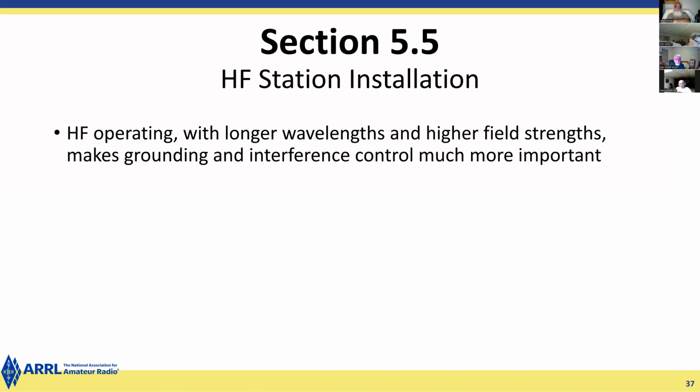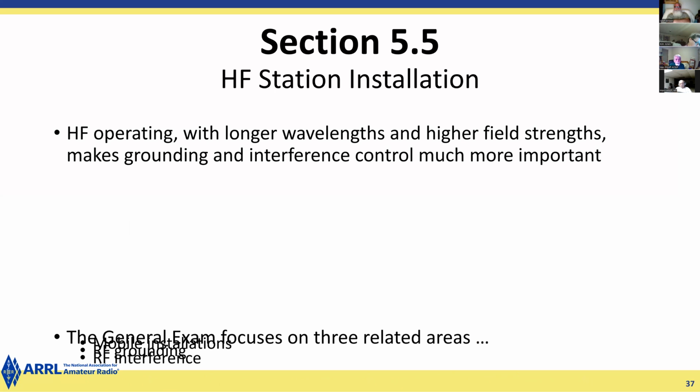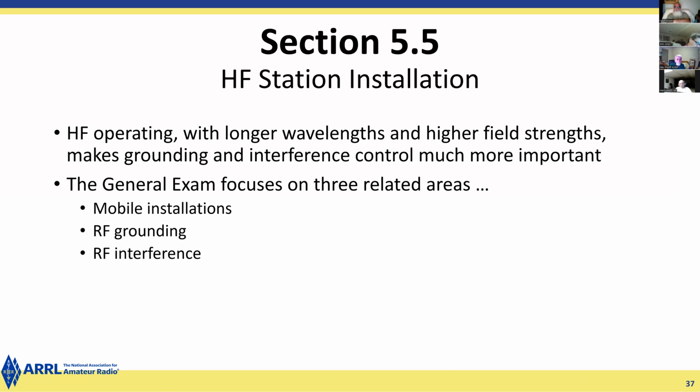So what you need to do is watch out for the consequences of longer wavelengths, higher power, both the amount of power that your radio needs and the higher levels of radio frequency power. So that makes grounding and interference control much more important. And the General class exam focuses on these aspects that are different from VHF.